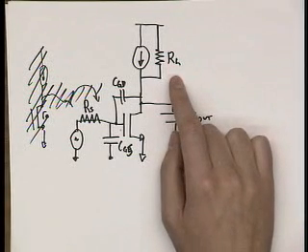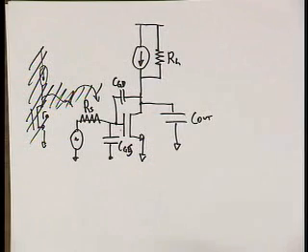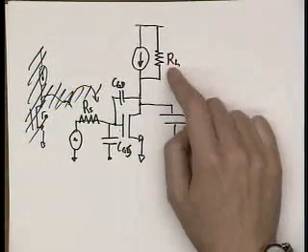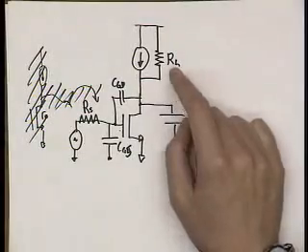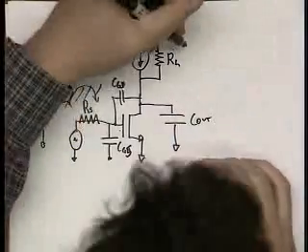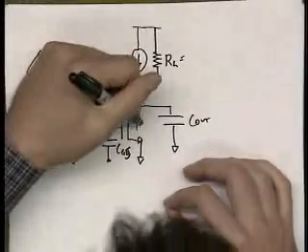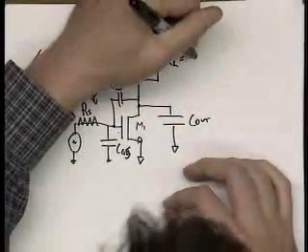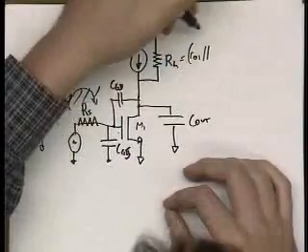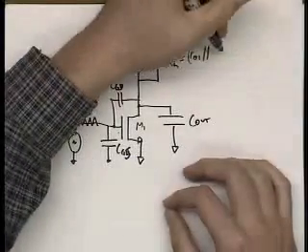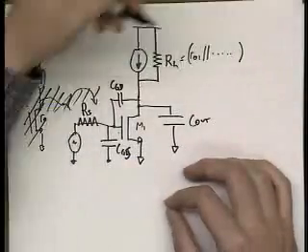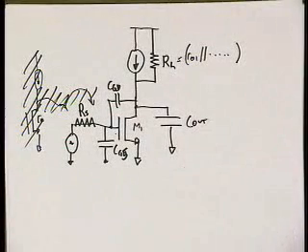It could be an R out of a PMOS transistor. It could be the R out of a cascoded PMOS transistor, in which case this resistance is very high. What I'm basically doing is lumping in all the resistances. So if we call this M1, this includes R out 1 parallel everything else, just to really keep things simple, to simplify it down to the core circuit.